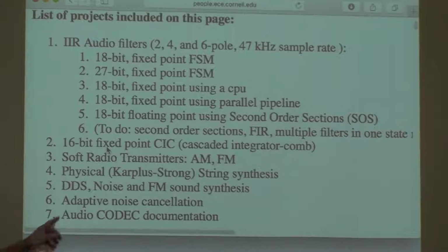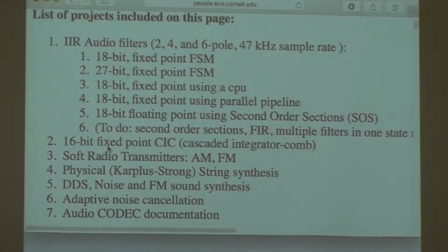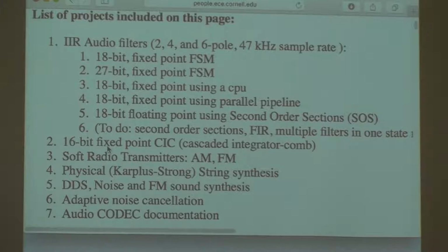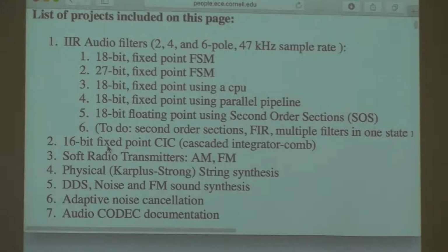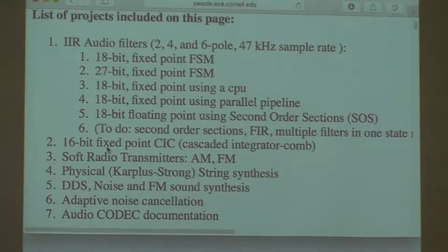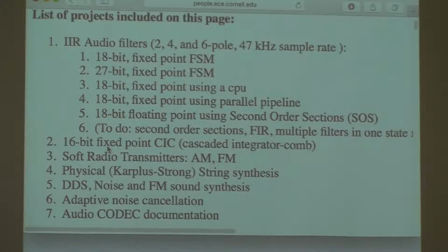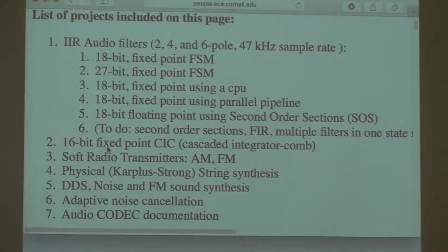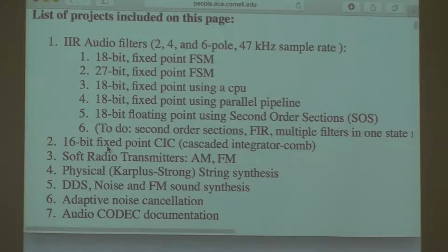And I messed around a little bit with adaptive noise cancellation. Narrow band. This was aimed at 60 hertz noise cancellation, so it uses a least mean squares filter. It's an adaptive filter designed to pull out 60 hertz and the low harmonics of 60 hertz. It's the second and third harmonic. So 120 and 180 hertz. Worked quite well. It was fixed point, didn't have enough accuracy, it's a little unstable, has a tendency to oscillate, needs work. But you get about 25 dBs of attenuation.